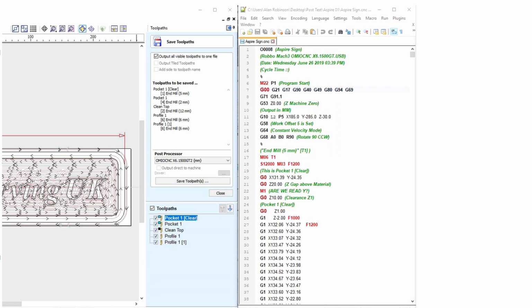It is an error if the D number is not an integer, is negative, or is larger than the number of carousel slots, the XY plane is not active, or cutter radius compensation is commanded to turn on when it is already on. The behavior of the machining system when cutter radius compensation is on is described in the chapter on cutter compensation. Notice the importance of programming valid entry and exit moves.